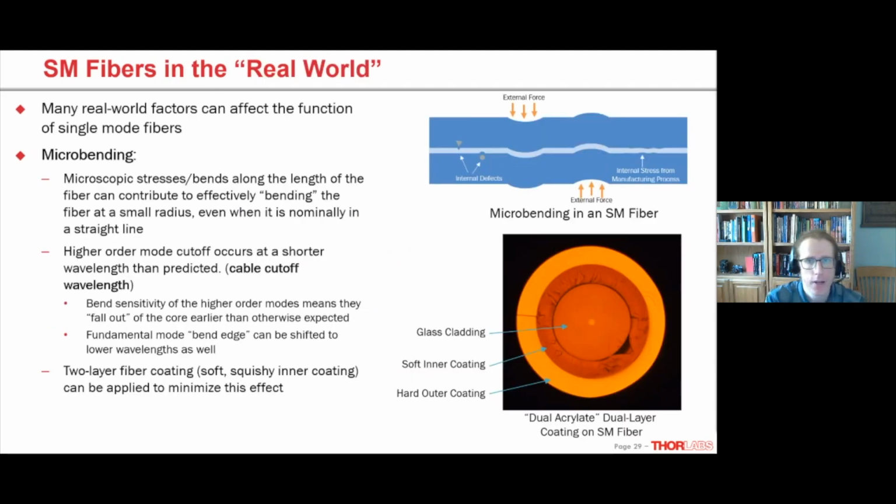Yeah, so basically a small defect is going to contribute to microbending. If you have a large defect, then scattering becomes an issue. In my cartoon here, I'm showing a defect in the cladding that perturbs that core-cladding interface. Let's say you had a defect in the core, that's going to straight up block the light if it's of sufficient size. So all these things are going to affect the performance of the fiber, in a way that's not going to help the attenuation.